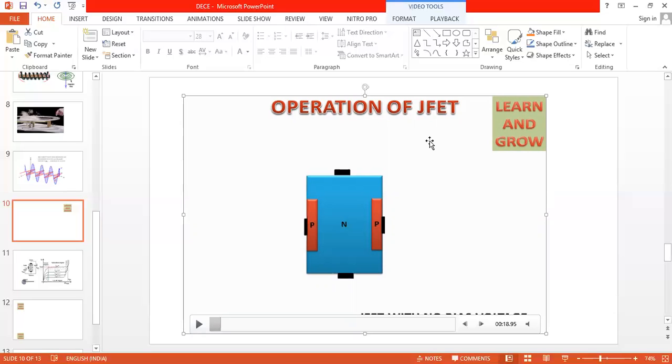Okay. Now, what is this JFET? What is the construction? FET, field effect transistor, we concentrate on the name later on. FET practically contains an n-type silicon thin layer on which at both ends p-type silicon material is diffused. FET contains three terminals: source, drain, and gate.